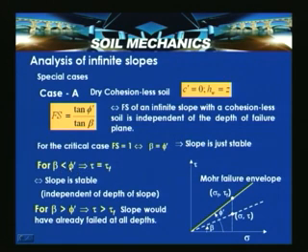Let us now plot this particular situation on a tau versus sigma plot, that is, a Mohr circle plot. Let us assume that this yellow line indicates the Mohr failure envelope, and this white broken line indicates the slope surface. Beta is the inclination which is shown here. This is the angle of internal friction, that is phi dash. Now if you look at a certain depth, let us assume that this particular point has coordinates sigma and tau, and this point is sigma f and tau f.